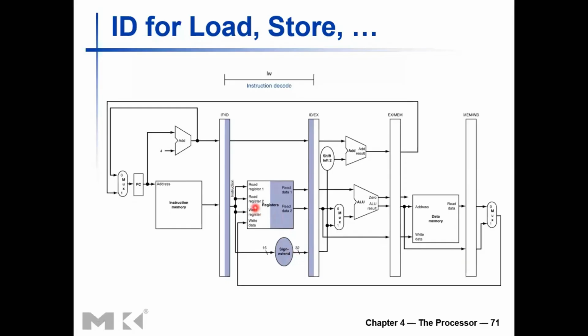For the register file, you're doing asynchronous reading. That reading happens after the pipeline register was written to and read, and the output will be available. By the end of the clock cycle, the values of the two registers that you read should be available here. The sign extended immediate value should be available here, and the PC plus 4 value from the previous pipeline register should also be available here, right? So again, a lot of information.